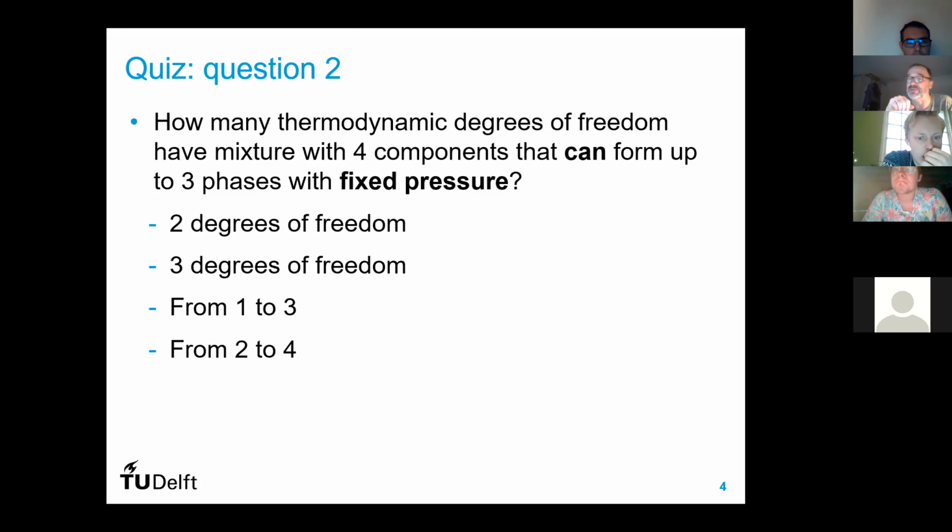And this is the thing that usually you mix, for example, hydrocarbon gases with water, hydrocarbon gases, liquids, and water. So I know that at most it can form 3 phases: the vapor hydrocarbon phase, the liquid hydrocarbon phase, and water, because water would never mix. It's its own phase by itself. So that means when I'm mixing these things, I can expect from 1 to 3 phases, in all kinds of